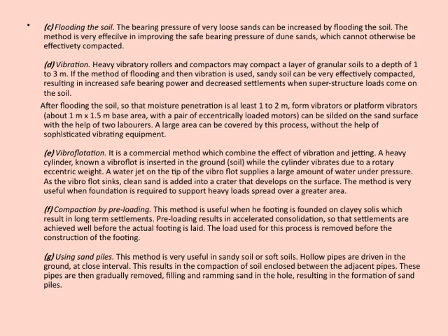Next, we have vibration. Heavy vibratory rollers and compactors can compact granular soils to depths of 1 to 3 meters. When combined with flooding, where the soil is saturated to a depth of at least 1 to 2 meters, and vibration, sandy soils can be compacted very efficiently. This process results in higher safe bearing capacity and reduces settlements under load.